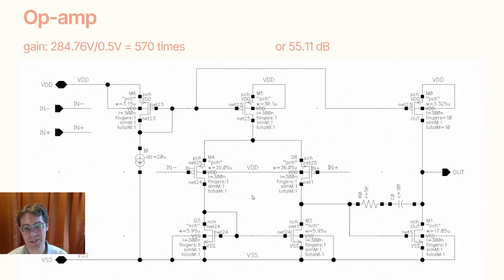These were designed at the transistor level, so the dimensions, like the length and width and the number of fingers on each one, were all things we were able to adjust in our pursuit of getting the correct component. And it was very important to get this component right because it's the core of the amplifier, and it was also used as a comparator for the analog to digital converter.